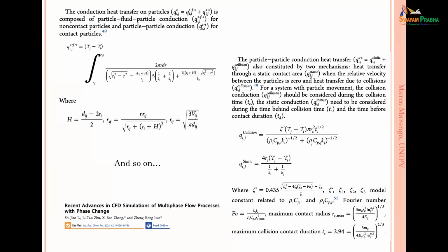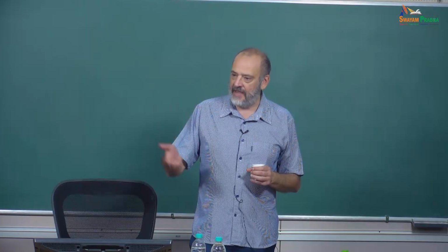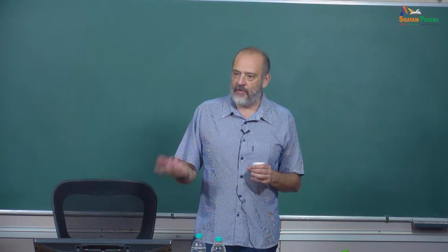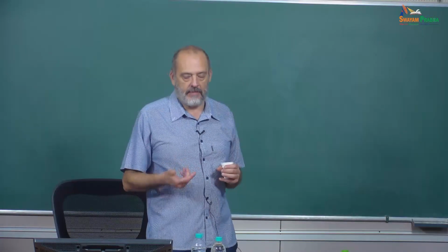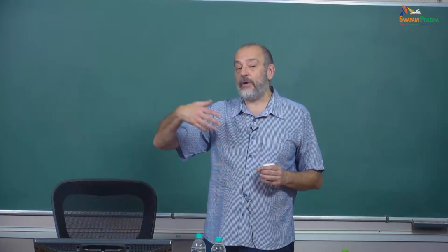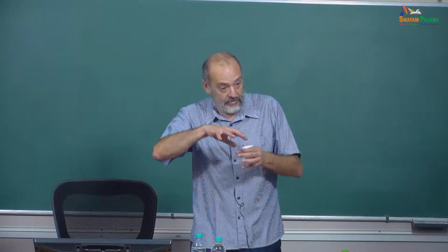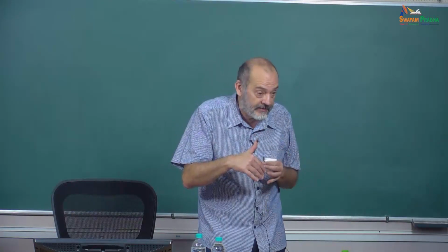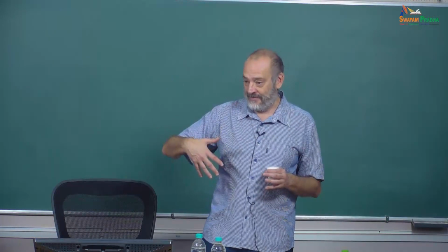If you want to read more, there is this paper from 2023, because this is part of research now. One can think that it's consolidated and everybody knows how to deal with this, but it's still research. As I said, all these coupling forces, coupling energy, heat going from one phase to another, is a question of tuning in many cases. It depends on the material, for example, the conductivity of the particles, and how we can deal with the conductivity of the parcels, because the parcel contains many particles, maybe with different conductivities, because we may have different components of solid particles.